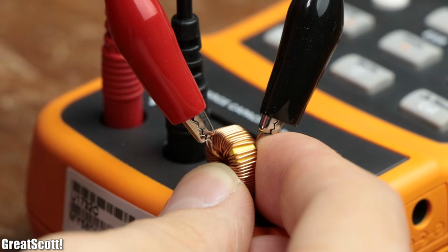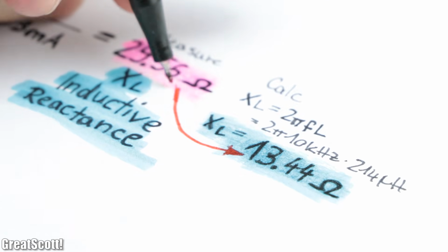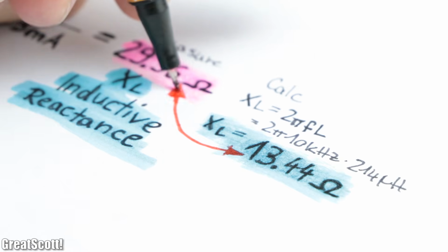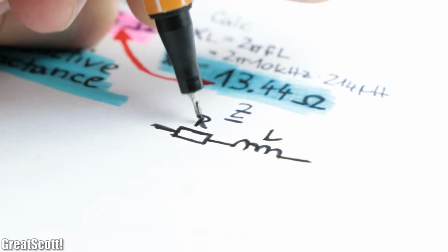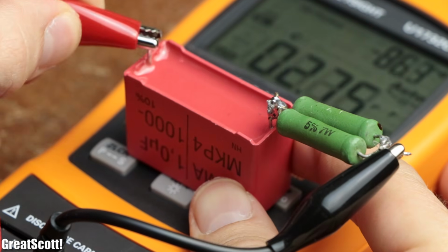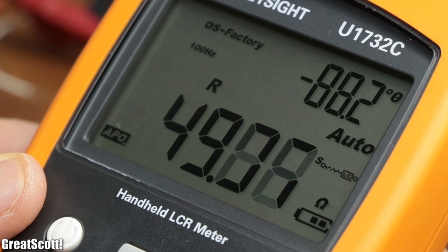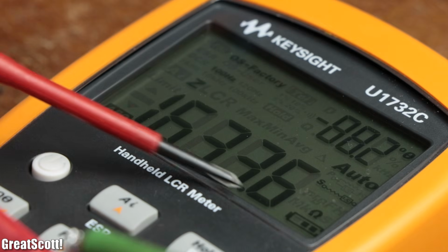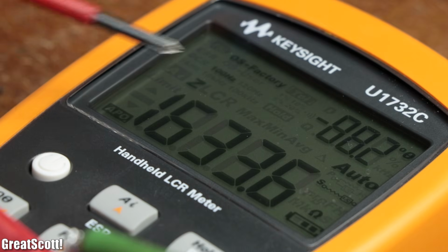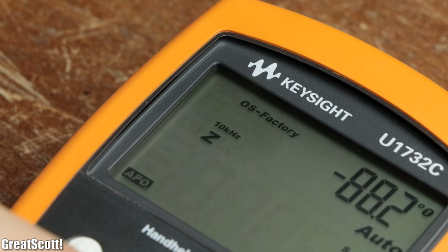In the case of the capacitor, they were rather small, but if you would look at a practical inductor, then you can see that the previously measured reactance is far from the calculated value, meaning it has tons of parasitic resistance. And by the way, by utilizing a good LCR meter, you can not only measure the capacitance, resistance and inductance, but also the complex impedance with its magnitude and phase angle, but only for certain frequencies.